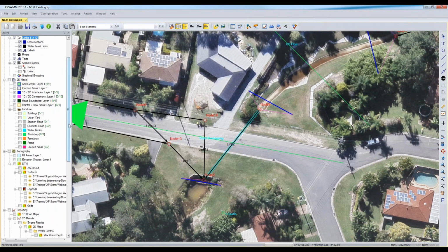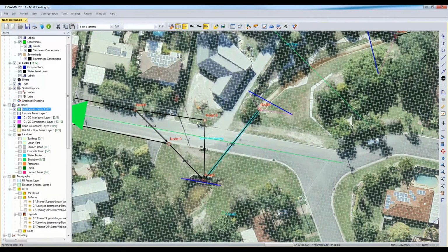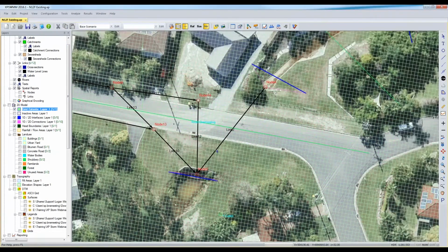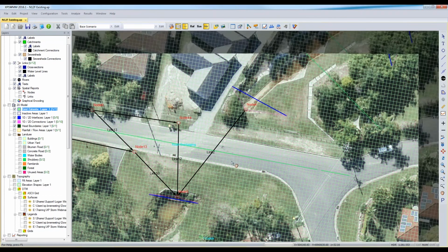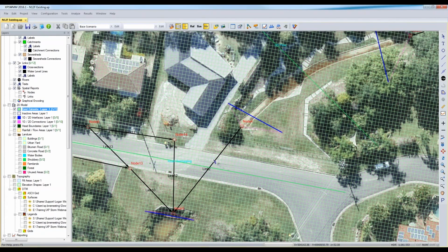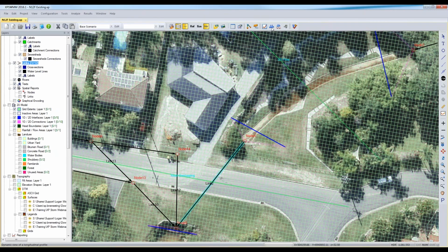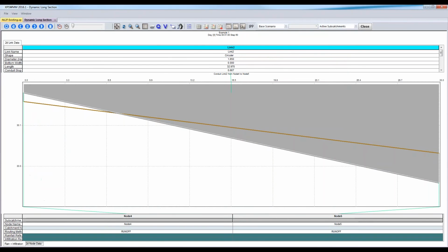What's probably happening, just to give you an idea of how it works, is that if that one line is outflowing, connecting through two 1650 pipes, it's trying to push the flow into a grid of 1 metre by 1 metre. That's going to cause an instability, so that's why you have these interface lines. It's worked in the past when we haven't had an interface line, but it connects through the 2D water level with the 1D line, and you can actually see if I run a long section, it does connect through how you'd expect it to look.